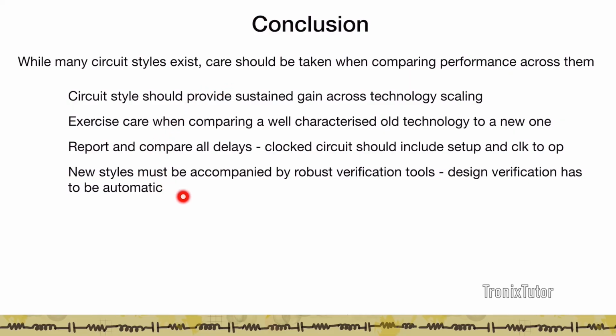And so with all this becoming increasingly complicated, you end up seeing most of the designs today use static CMOS or some sort of skewed static CMOS. And we see that the dynamic and domino gates are used sparingly in very specific niche areas.